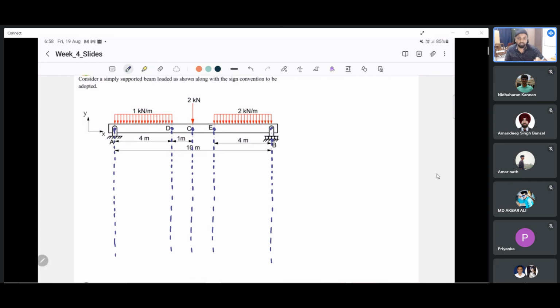I'll do it a little fast so that we are able to solve something today. I'll represent this by AY, and this by AX. And I have an upward force BY here. Now if we take sigma Fx equal to 0, Ax comes out to be 0. I won't solve it because that is the only horizontal force applied.